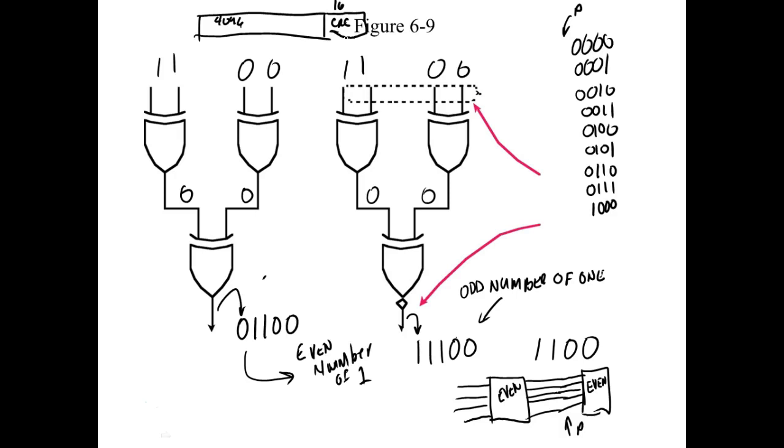Because 4,096 bits would be how many bytes? Well, if I was using parity, we would have 1 parity bit per byte. But if I'm sending 4,096 bits, y'all understand, then I can sacrifice 2 bytes of data for CRC codes. And the CRC code, a 16-bit CRC code, so I sacrifice 16 bits to be 99.999% accurate.